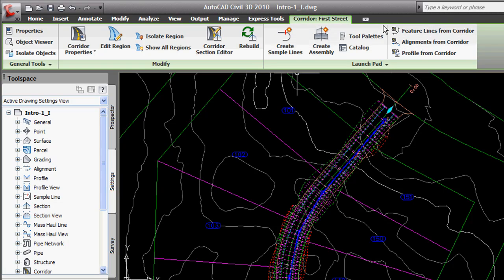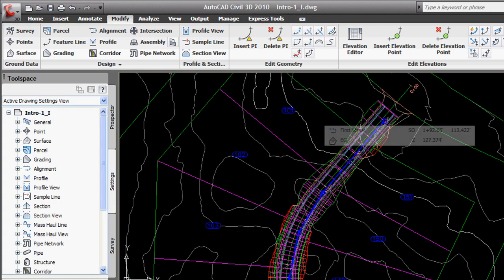And what that means is, notice we don't have a close button over here. So I've selected the object. Once I perform the edits, then this tab will disappear. So I have the corridor selected right now. I could change something about it. When I'm done, if I deselect, so I hit the escape key, deselect the object, it returns automatically back to my default ribbon view.